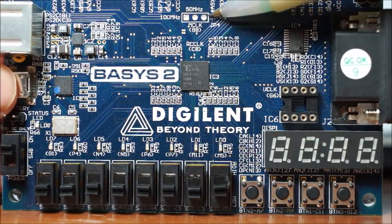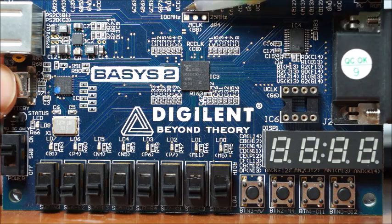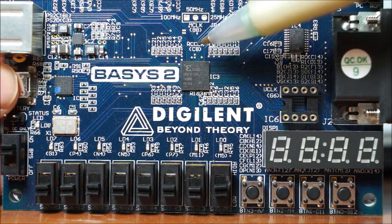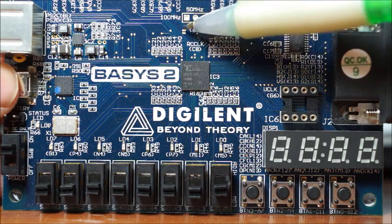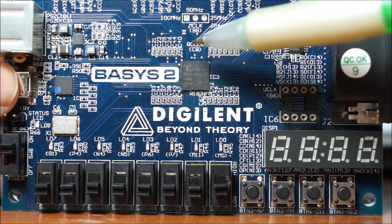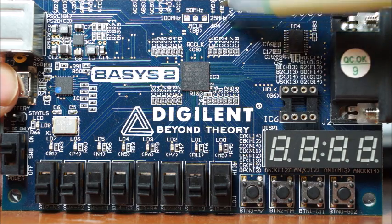You get this jumper over here, which you can use to change the default clock frequency. The default clock will be set at 50 MHz if this jumper is left open. You can select between 100 MHz and 25 MHz based on your preference.